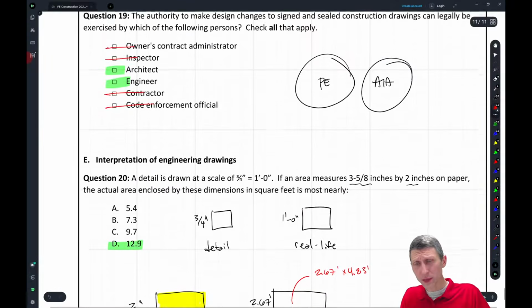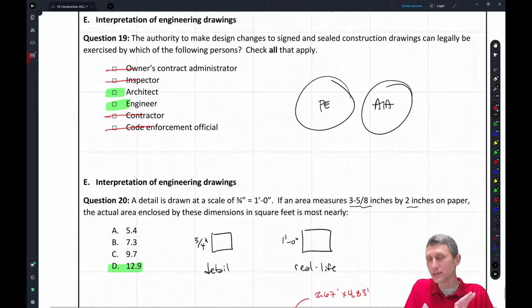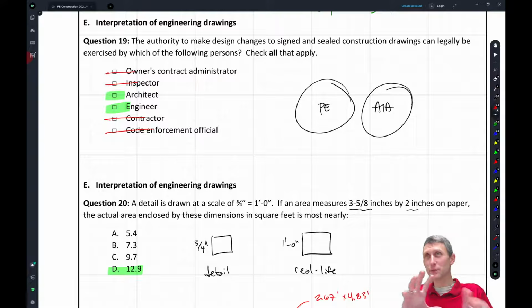So the question is, when do you need an engineer stamp versus an architect stamp? Typically, architecture deals with the first set of chapters of the building code, with occupancy, egress, and fire safety. Those are the big pieces of the architectural. You want to make sure the building occupancy is specified correctly, egress so people can get out in the event of a fire, and fire safety really. So you've got the right doors, hallways, corridors, stairwells, fire protection systems, firewalls where there need to be firewalls. You have building separation, building maximums, that sort of thing.